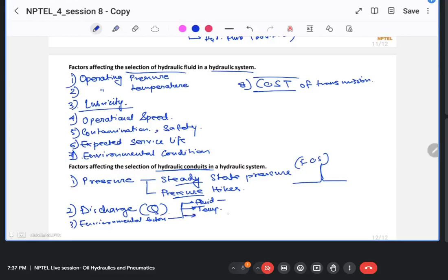Next, vibration is another important thing. As you know, when there is vibration, there are chances of losing components, like the components becoming loose when you have some threaded parts. Accordingly, you should be choosing the fittings so that they don't become loose during the operation. Otherwise, there will be possible chances of leakage.